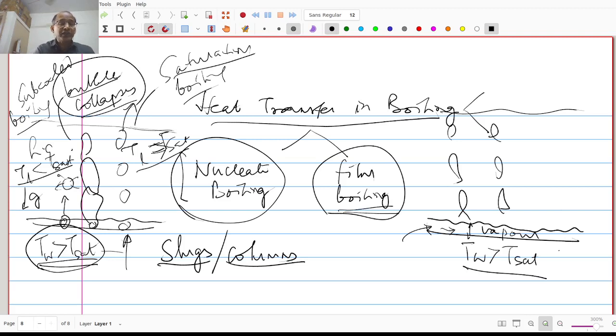So when the nuclei are separate, it's called nucleate boiling, and when nuclei merge together and form a stable film, where heavier liquid is standing on top of a lighter vapor column reasonably stably, because of the rate at which vapor is formed, we get what is called film boiling. And as the heat flux is persisted, and the rate of vapor formation increases, and the stable vapor is there, the solid surface temperature goes up.